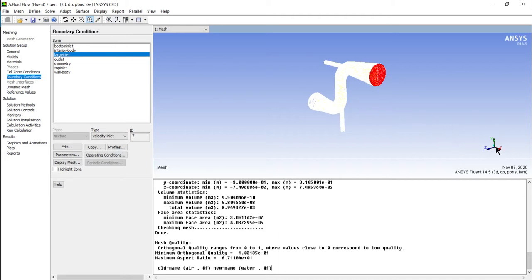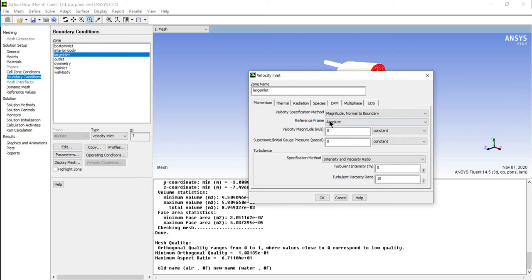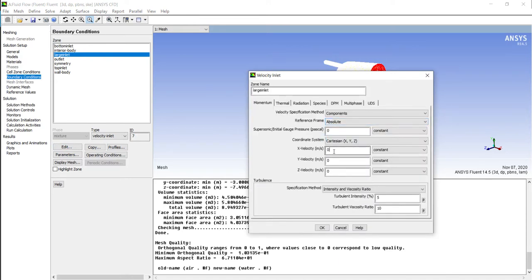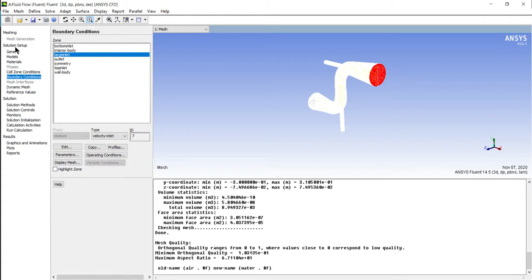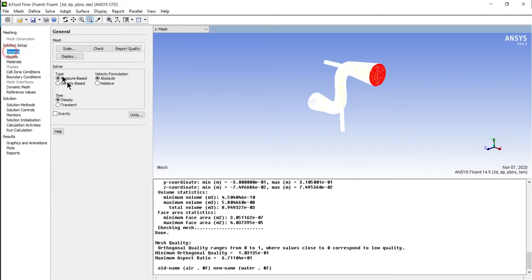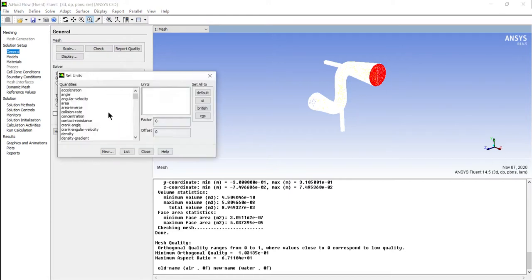with respect to x direction now, yep, flow is with respect to x direction, that I need to analyze. So inlet should be with respect to x, the component, it should be 0.4 meter per second, fine. And then here the turbulence method with respect to diameter, so the diameter is 150, that I know, I'll mention it here, 150 meters. Okay, I need to change the units, not meters, so let me just check my unit system. The general unit should be with respect to length, it should be meters.